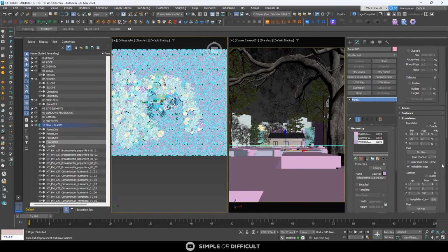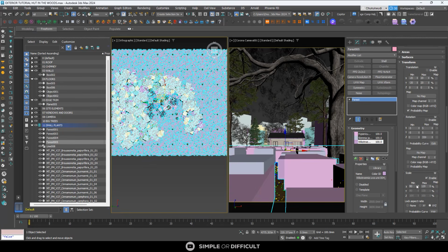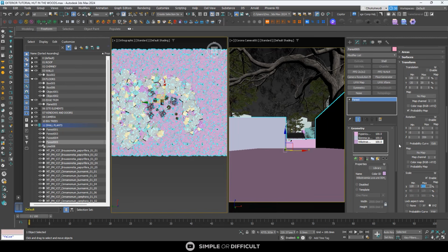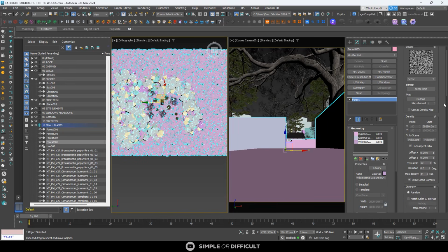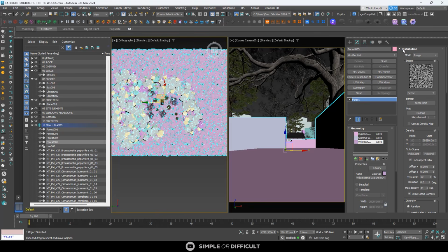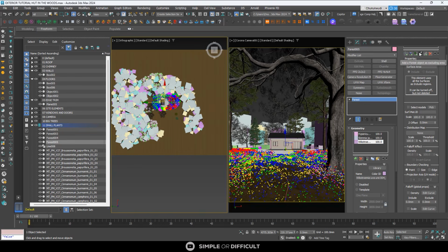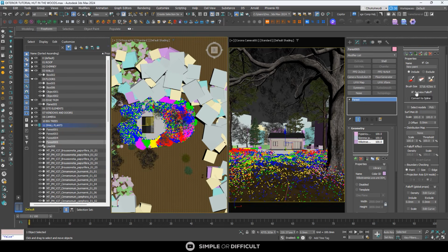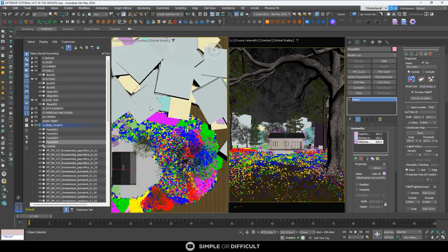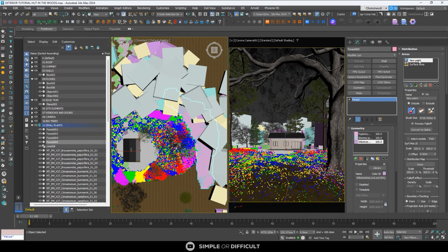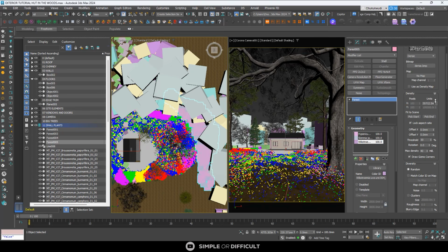All right, so I'm going to come here in the transform, enable this, make this 120, 200. Then I'm going to go over to the distribution. Now the area, turn it off, use paint. We're going to add this only on the areas behind our camera. So let's go back to distribution and ensure that we open it up.